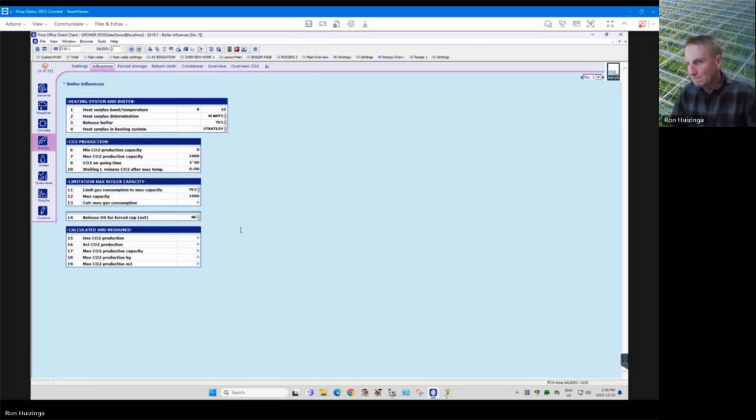Okay. And theoretically, if they want 9,000 parts per million of CO2, is that possible to get? The meters only read up to 3,000 ppm. And typically I think there's a labor safety rule in Ontario that you're not supposed to be over 1,500 ppm for more than so many hours or something like that. It's not safe for employees. So you said 900 or 9,000? 9,000 to kill pests, I guess.